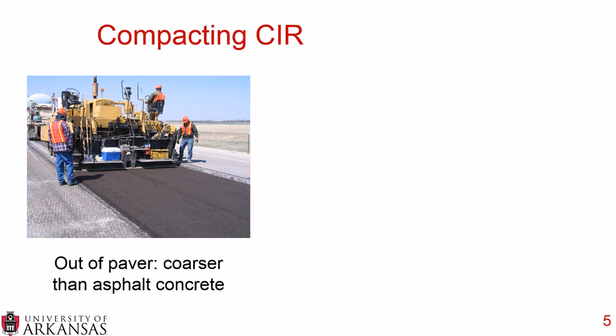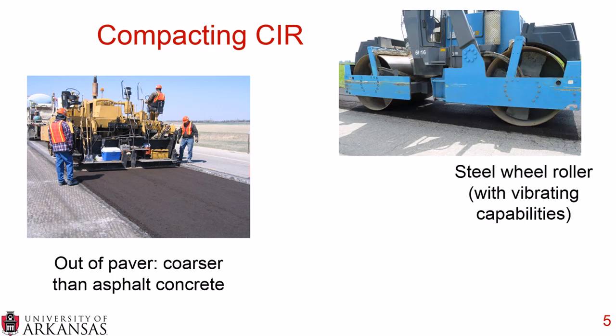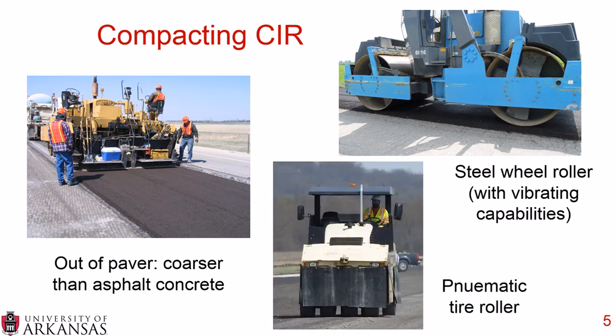And after this comes out of the back of the paver, you then compact it with a combination of steel wheel rollers, and some of them have the vibratory mode on, and then other passes they do not. It's a static steel wheel roller. And then you also have a pneumatic tire roller. And there's some sort of combination of these steel wheel and pneumatic, and the steel wheel may or may not have the vibrating capabilities.